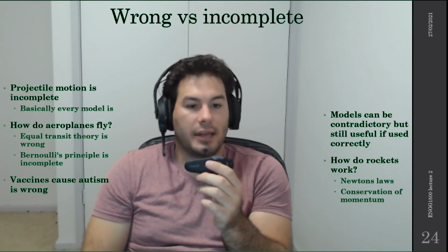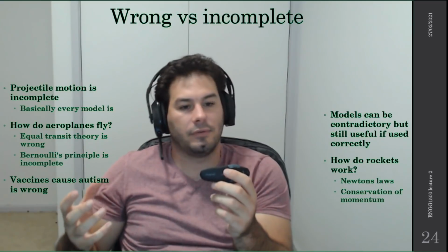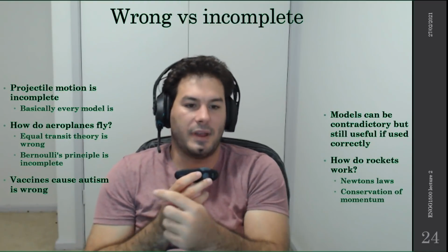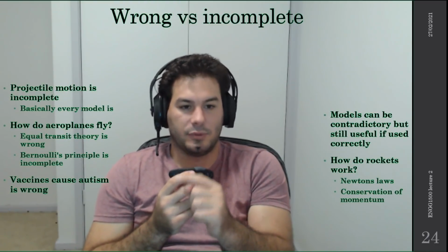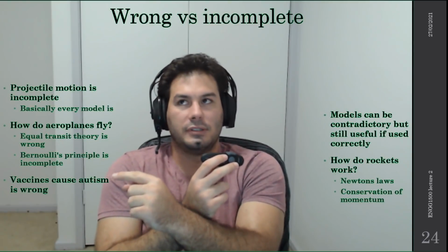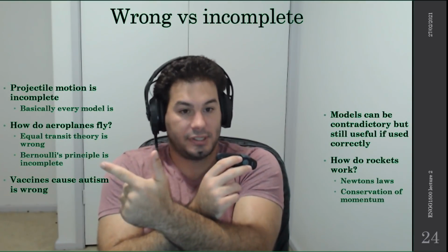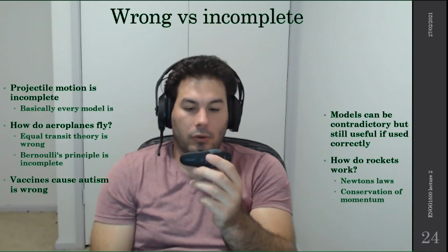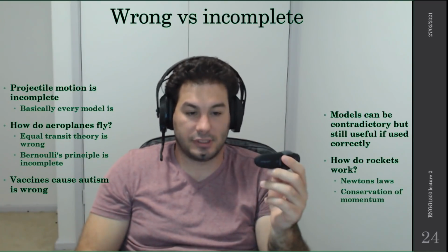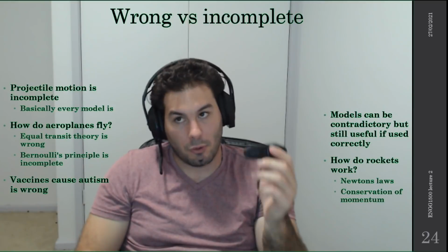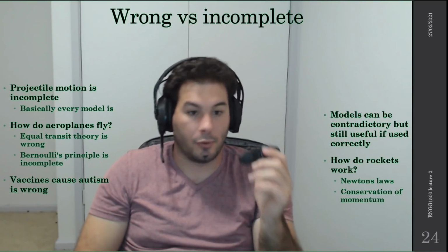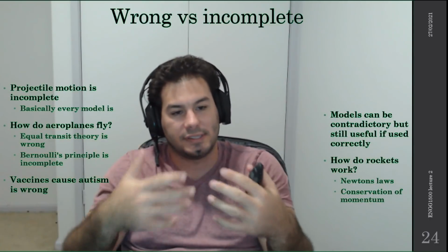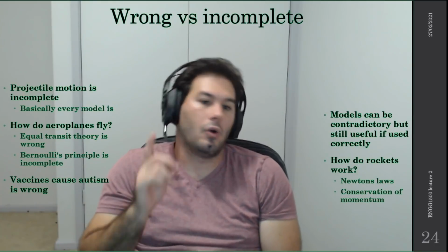There's a really simple way, and it's a totally different approach to modeling. Instead of looking at thrust and stuff from Newton's three laws, we look at it from a conservation of momentum perspective, and we say hot exhaust gas was ejected backwards with a mass and a velocity, meaning it has a momentum. In order for conservation of momentum to hold, our system as a whole thus needs to displace forwards with the same momentum. We know its mass, therefore we can calculate the velocity that it will be moving forward at. And so it's just a totally different approach to the same problem. And you will see this all the time, okay? So there's not one way to model something.